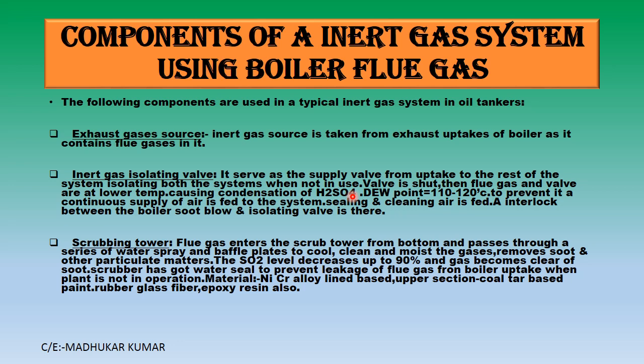H2SO4, because the flue gases are there on the valve side, and if it is not being used, condensation can occur. The moisture content will react with the SOx and form H2SO4. The dew point is about 110 to 120 degrees centigrade. So at this point you have the dew formation and the formation of H2SO4, which is highly corrosive in nature.